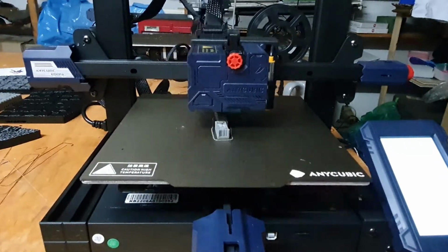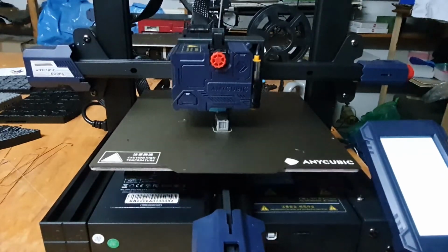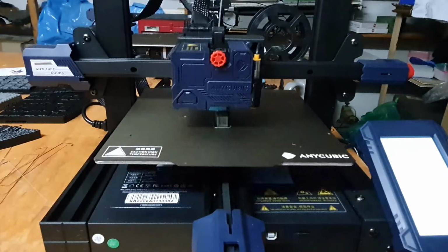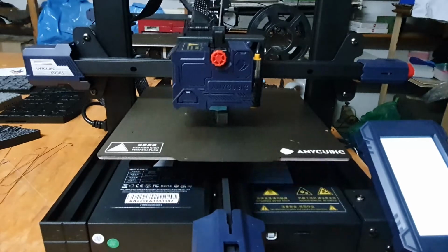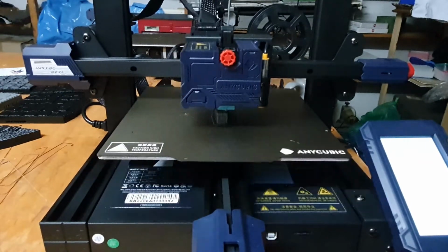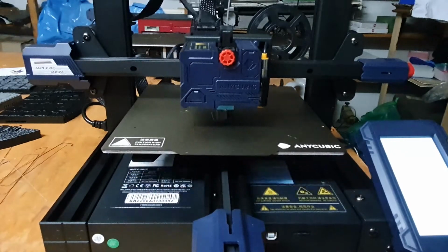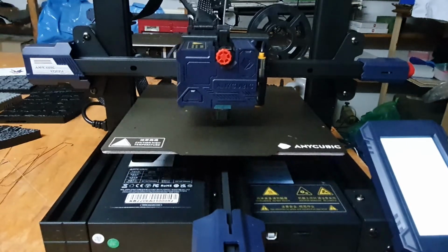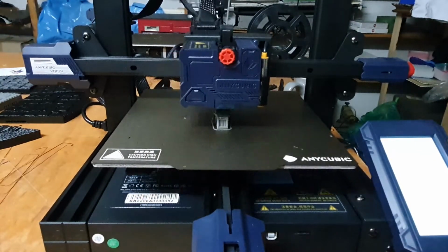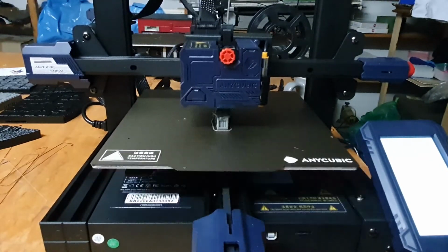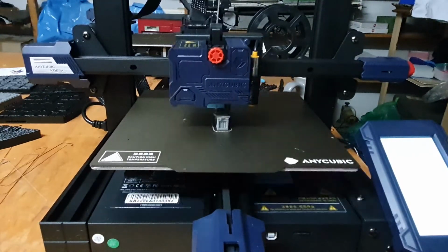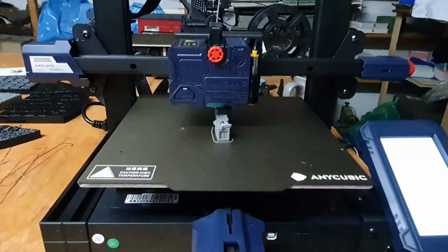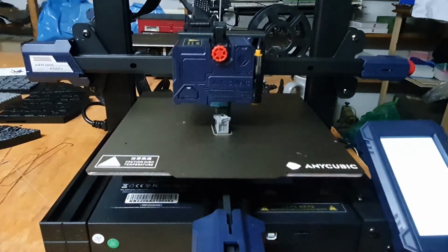The problem I have with these machines is if something doesn't work as it should, then you have to troubleshoot. And these machines have a lot of sensors, a lot of motors, a lot of electronics that can go wrong. They have wearing parts. You need to replace and clean the nozzle regularly. The filament can get clogged up. So maintenance and troubleshooting is not necessarily easy and is, in my mind, the biggest downside on these machines. Other than that, they're great.